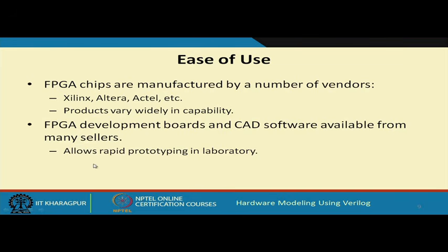Now, anti-fuse is something a little different, it is one time. So, by passing a high current between 2 points, I can connect a connection. Now, anti-fuse means normally there is no connection. So, if a high current is flowing, then the material will be fusing, it will be melting and a connection will be established. So, there are some FPGA manufacturers which also use this kind of anti-fuse technology. Fine.